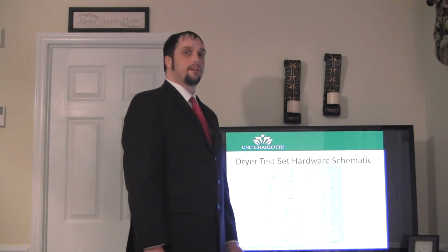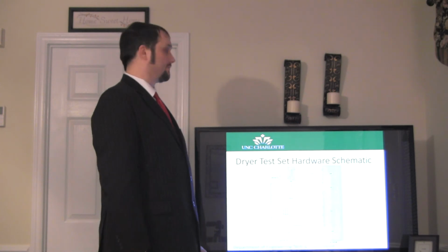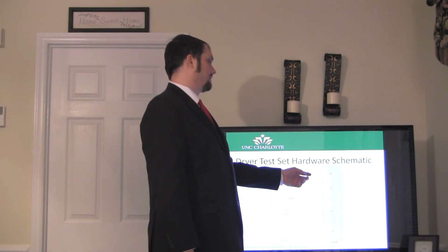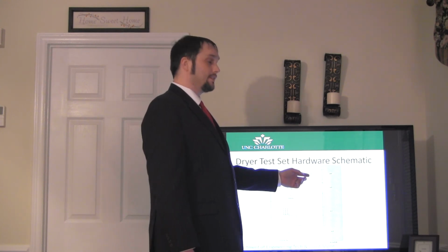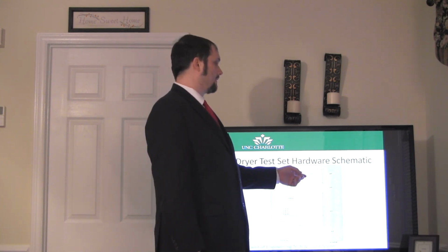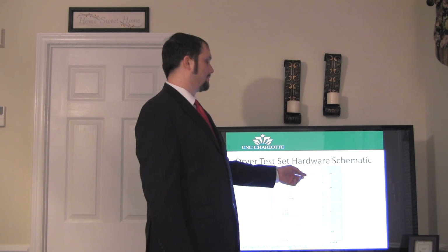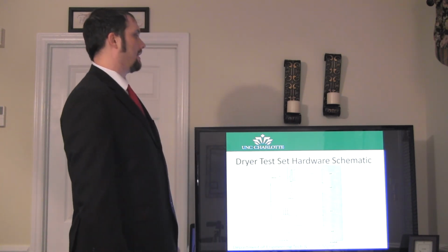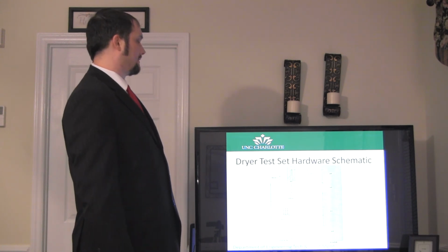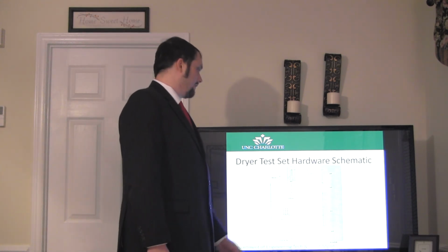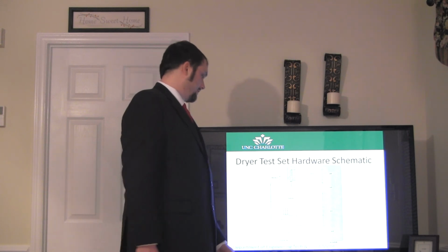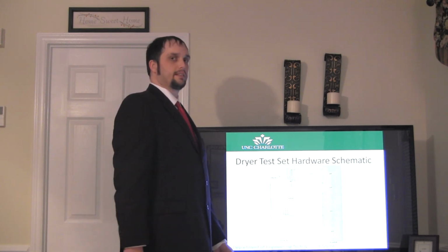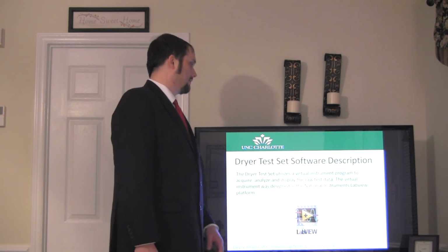They produce a current from 0 to 20 milliamps full scale, and this is a 276 ohm shunt resistor that the current produces a voltage drop across that is monitored by AI0 and AI1 respectively. Your data acquisitions card is connected by USB to your computer. So that's how all the data gets into LabVIEW, is through your data acquisitions card.